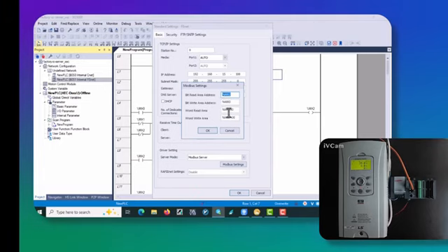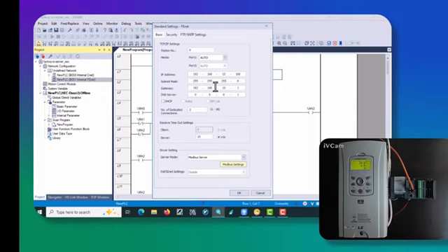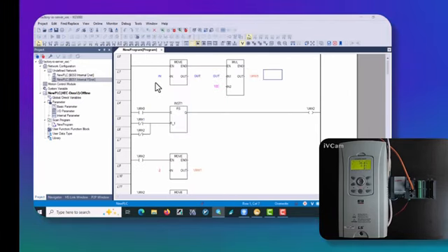I confirm this. But I need to make some settings related to the IP address. The IP address for my Factory I/O needs to have the same subnet ID as my PLC. I have correctly selected the PLC. So my PLC's IP is 192.168.15.100. The gateway I also selected is 192.168.15.1. Alright, these are the settings related to Modbus TCP in the XG5000 software for the LS PLC.